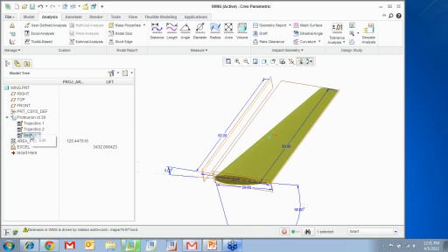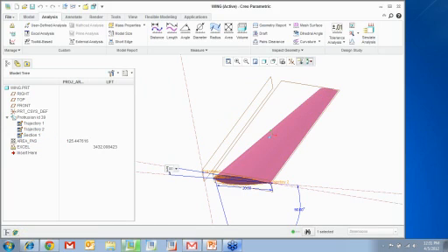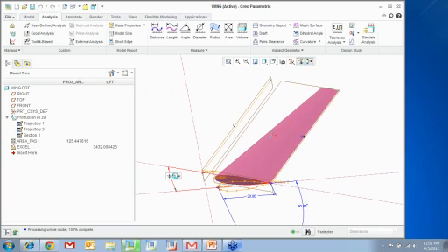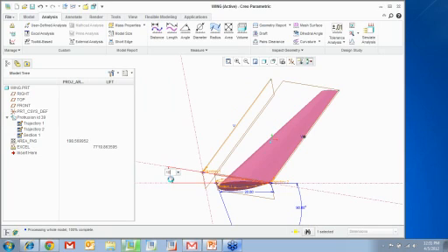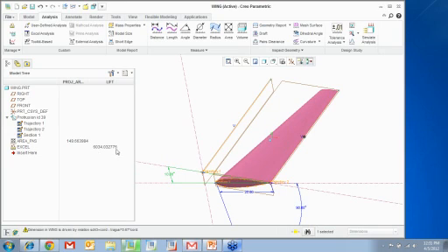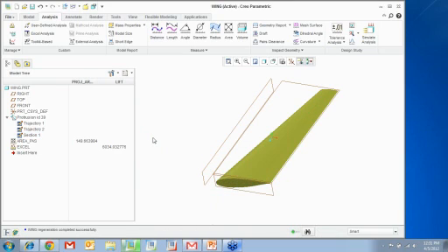So if I go ahead and edit this value to say I want to go 15 degrees, like that, you can see how your lift and your projected area changes. You can go ahead and make it 10 degrees, and you can see how your area and your lift force changes. Right? So we can use an Excel file to determine a lot of things within our design. Okay? So that was Creo Simulate and Creo Excel analysis.